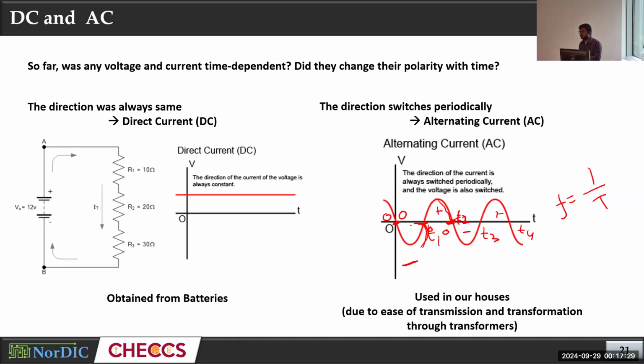So the voltage that we use in our homes is around 200, 220 volts, right? But when we first supply the voltage from the power grid, it's in thousands of volts. Okay, thousands of volts. AC signals also have losses on wires and resistances, similar to DC. But if you start with 1000 volts, how much can that lose? We will still have some hundreds of volts after losing in the wires, even if you distribute that through hundreds of kilometers.